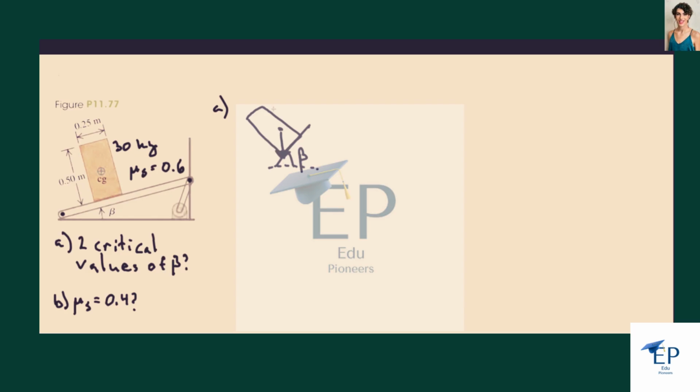So this is not drawn to scale properly, but the torques from N and F equaling zero implies that the torque from the weight is also equal to zero, which means that the moment arm from the center of mass has to pass through this point.